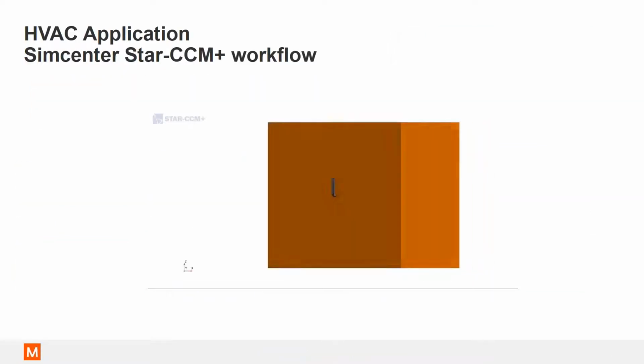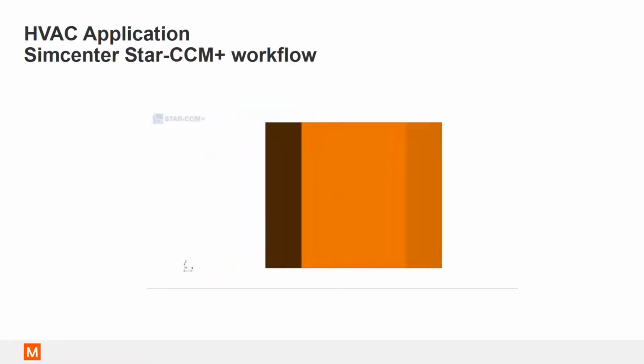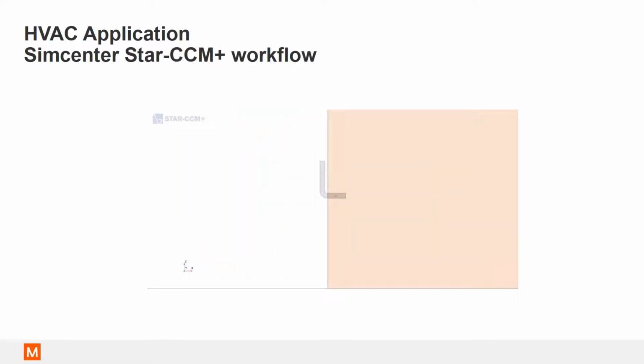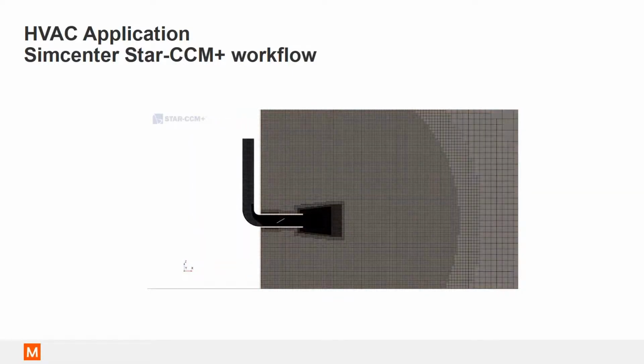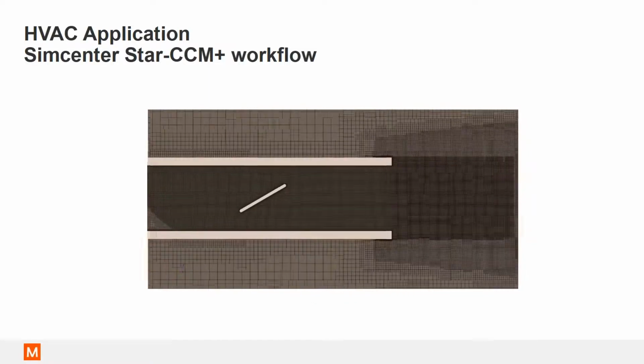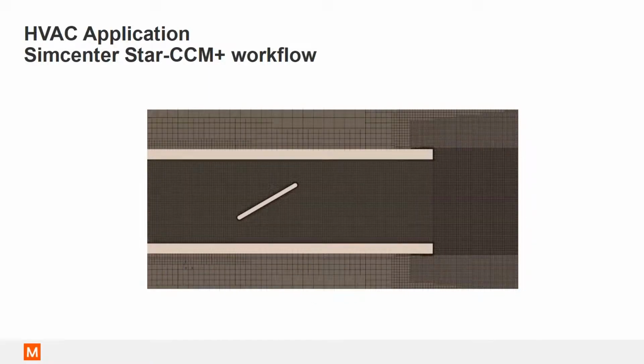But before we begin running the full CFD model, you want to run an initial CFD mesh based on experience essentially, and you want to capture the pressure fluctuations. In our case, we want to capture the pressure fluctuations caused by the flap in this HVAC duct and the free surfaces of the duct itself.